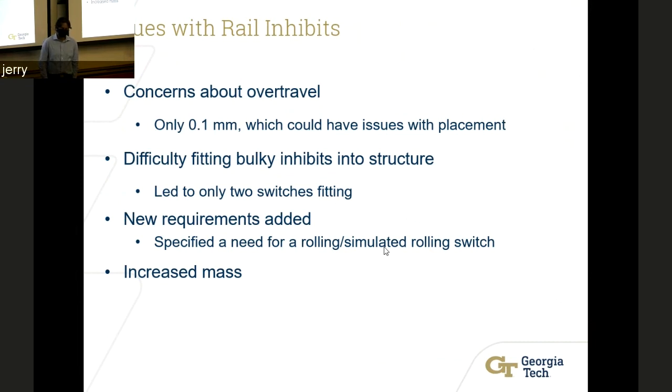So the side switches are better in terms of their reliability and potentially having fewer issues with vibrations. Our main concern was the size of them and trying to actually fit them in. It was mostly because we were nervous about human error leading to a lot of issues. Because of how tight the spacing was, we were concerned that if we placed the sidewall switches improperly during integration, with such small spacings allowed for the switches, more issues could arise.